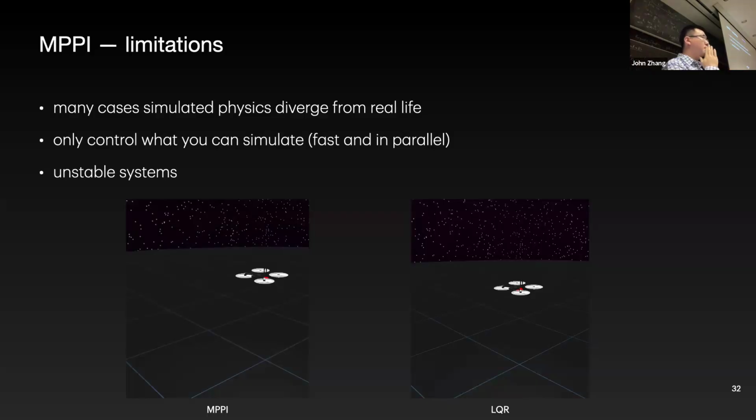Does that work better if you have a shorter time horizon? Yes. In the limit of a really short horizon, it's fine. But then you need a really good estimate of your terminal cost to make that work well. Typically, if you want to get around the single shooting ill conditioning issues, one, you can simulate with some feedback policy, which is what iLQR does.